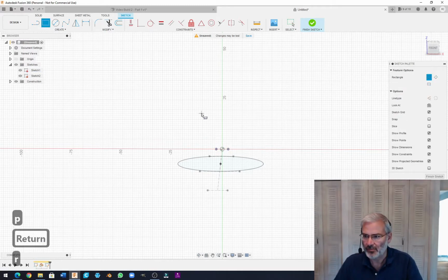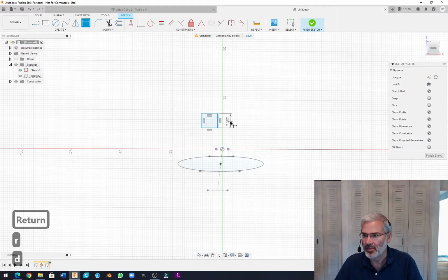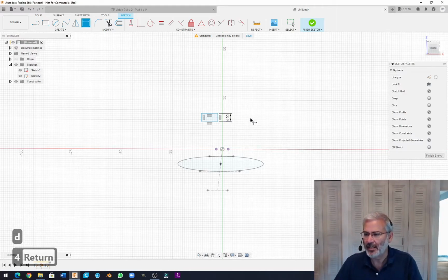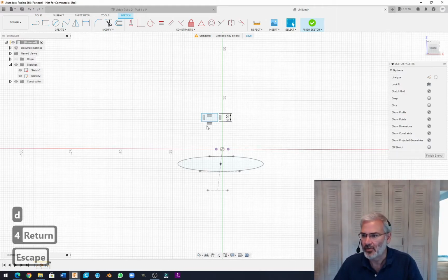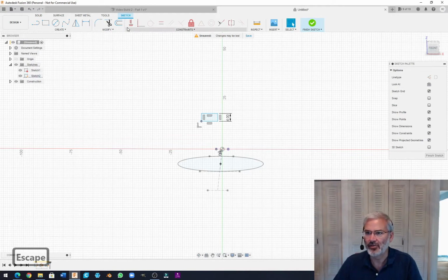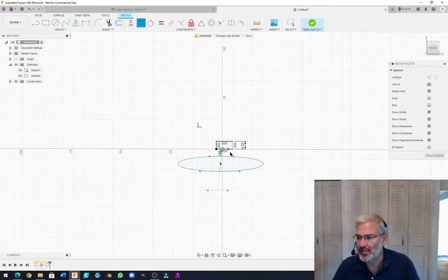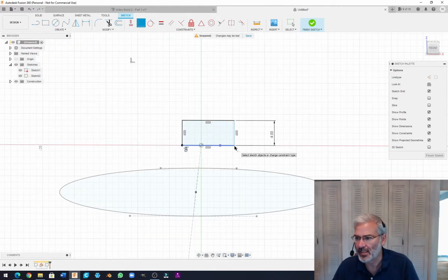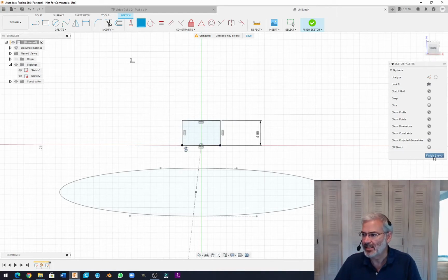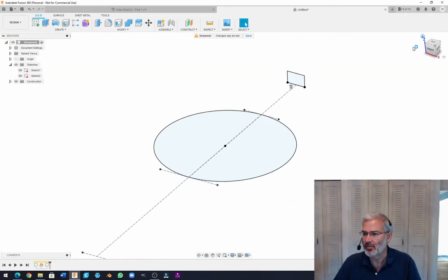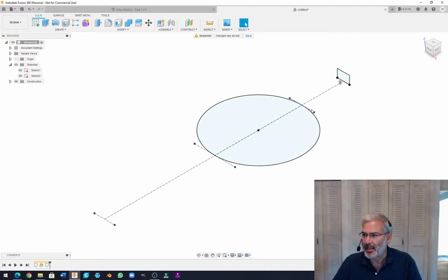And we want to use the rectangle command here. And we want to dimension these to the aforementioned 4 in height. And of course the width will be prescribed by constraining it to these points here using the coincident constraint. And then we'll zoom in and do the same for these 2 points. And that completes that sketch. Return our model. And now let's do the next one.